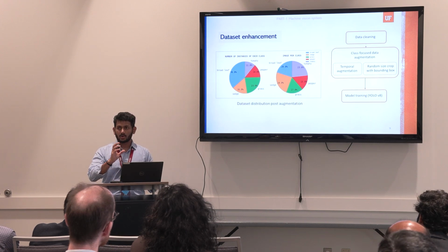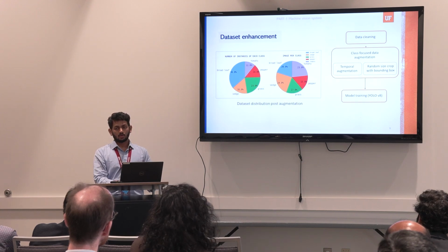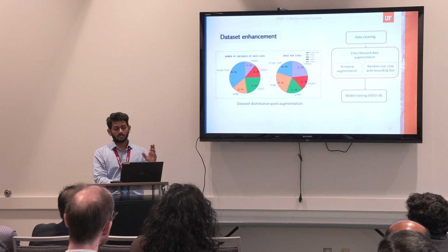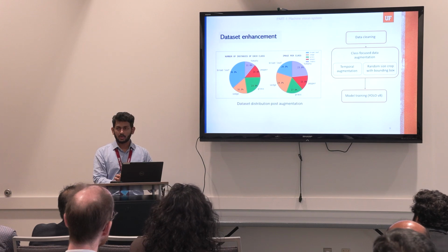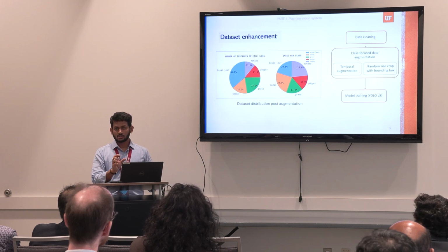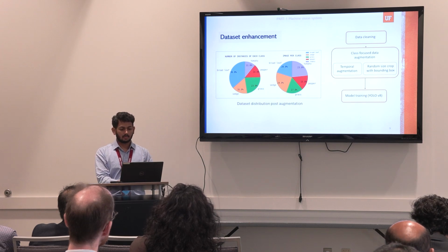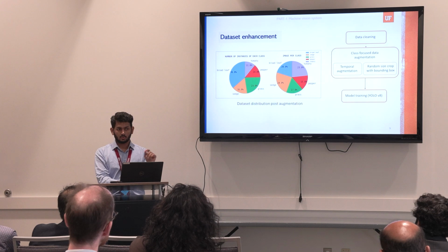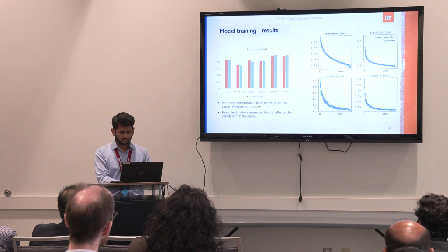Like I mentioned before, I have 16 zones in this robot, and based on the location of the weed, I get the nozzle information in terms of the zone, and I send it back, and then we send it to the spraying system, which then triggers the appropriate nozzle belonging to that zone.